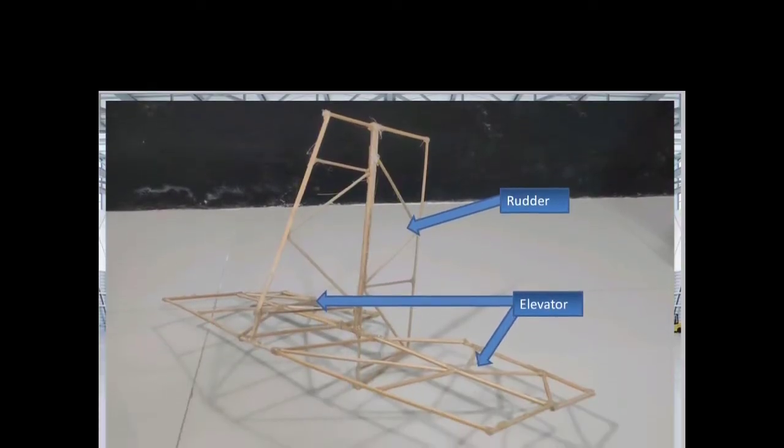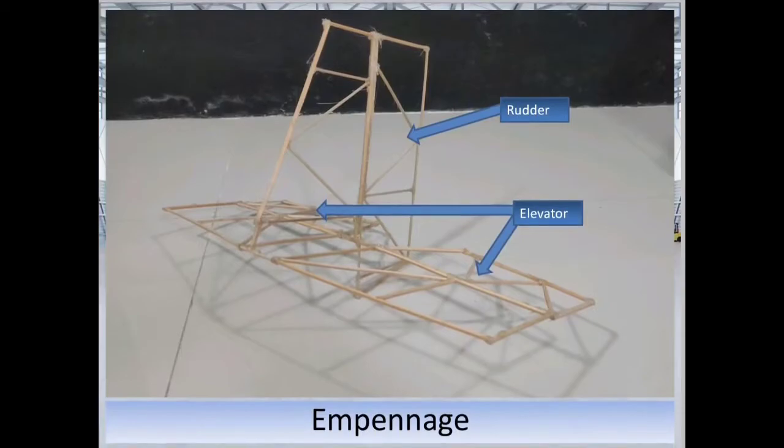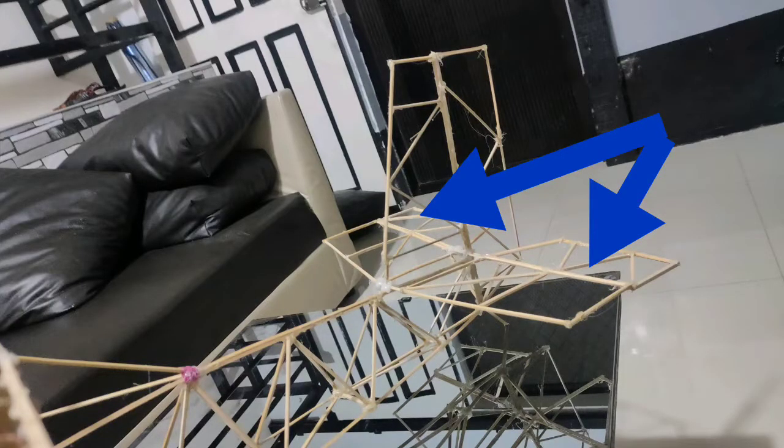The hinged part on the horizontal stabilizer is the elevator and is one of the primary flight controls. When the pilot in the cockpit pulls back on the yoke, the elevators go up, causing more force to push down on the tail, lifting up the nose of the aircraft. Raising the nose changes the angle of attack on the wings, increasing lift.